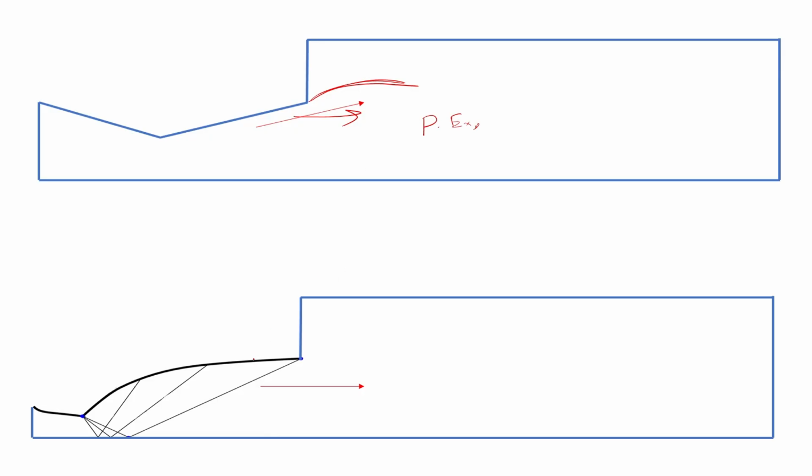Because for an original nozzle we would use a contoured nozzle, where the exhaust flow will be aligned with the free stream, horizontal. It won't be diverged like the simplified version we have taken. It should be a proper contoured nozzle designed using the method of characteristics. But just for the simulation I have taken a divergent one.